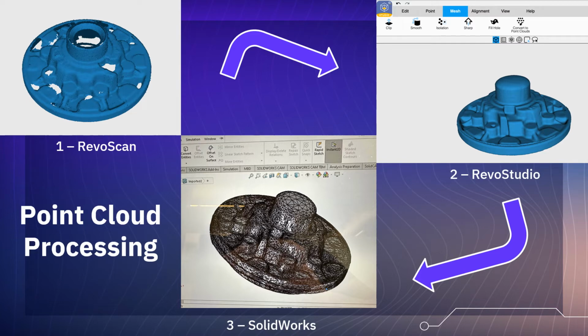Revo Studio will prompt the user to identify 3 shared points on each scan to help compute the complete geometry. Isolation. This feature automatically identifies and deletes point cloud data that is detached from the main body of the part, resulting from errors in the scanning process. This is an important step to eliminate unnecessary noise. The clipping tool allows for further manual removal of unnecessary points in the file. This is a simple task involving clicking and highlighting the desired areas to be deleted.